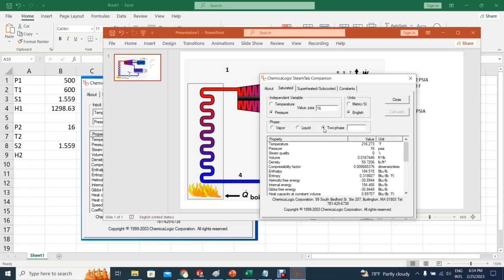That's where we are. The pressure is so low coming from the turbine or the expansion engine that there's some water on it. So the quality is not 100% vapor. It gotta be less than that. So I can show you what number you need to punch here, but it's a number between 0 and 1. If you put 1, let's put 1. Well, that means that it's pure vapor. So you will end up having an entropy of 1.74, I believe that was the number. Yeah, 1.75. Now, if you have all liquid, meaning you have a 0 here, calculate, but you end up way back again to entropy of liquid. So it's a number that is between 0 and 1.